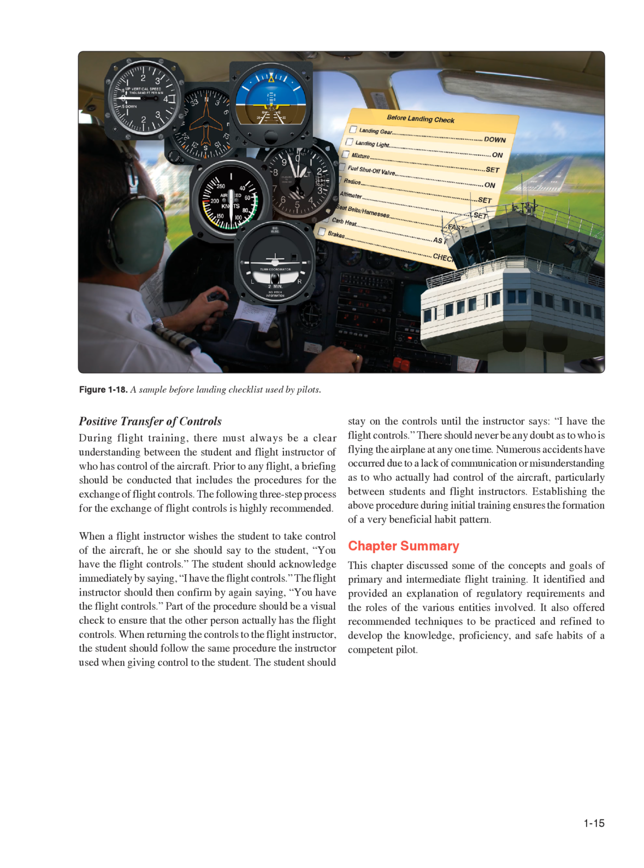When returning the controls to the flight instructor, the student should follow the same procedure the instructor used when giving control to the student. The student should stay on the controls until the instructor says, "I have the flight controls." There should never be any doubt as to who is flying the airplane at any one time.